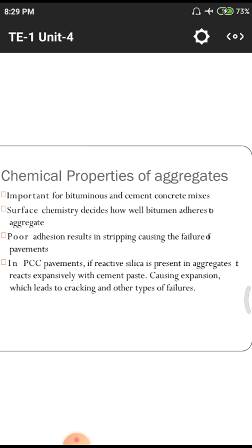So we had better understand that whenever we have to lay a particular quantity of road, we need to do some tests on the aggregates and these binding materials in the laboratories, like elongation test, penetration tests, surface penetration tests and water absorption tests. All those things we have to observe in the laboratories. Otherwise, if we simply construct on the pavements, for a normal road it is okay.